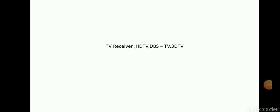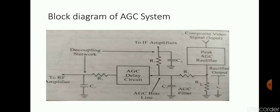Now we will see TV receivers. In case of TV receivers, we have a block diagram of AGC, that is automatic gain control. In TV receivers, the AGC circuit works like the volume control circuit in superheterodyne AM radios, which provides automatic adjustment of output volume against variation in the RF signal strength.